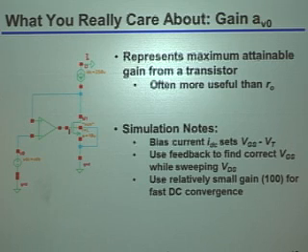So notice, like you were asking before, I didn't do anything at all to specify what VGS is, right? Because I don't actually care. Because once I've specified this bias current, and I've specified the size of the transistor, to zero order, I'm also specifying essentially the V star. And so I'm just letting this amplifier decide what the VGS needs to be in order to actually get the VDS I wanted and this so-called current density, or essentially this bias current, given the size of the device that I'm using. Yes?